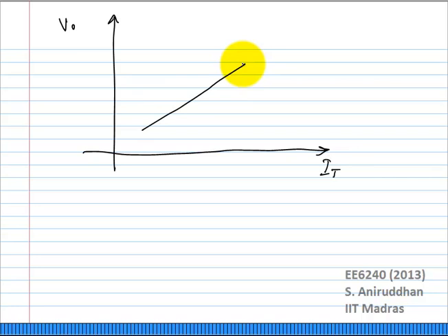Which triode region? The triode region. Okay, when does the transistor go into the triode region? Remember that we have said that the transistor primarily goes between on and off. It spends a little time in the triode region, but not a lot. Remember, these are cross-coupled transistors. They switch from on to off pretty much. So what happens if you keep increasing the current? Yes, I'm increasing the tail current in the tail current source. Let us look at this first. It directly ties in with your question.